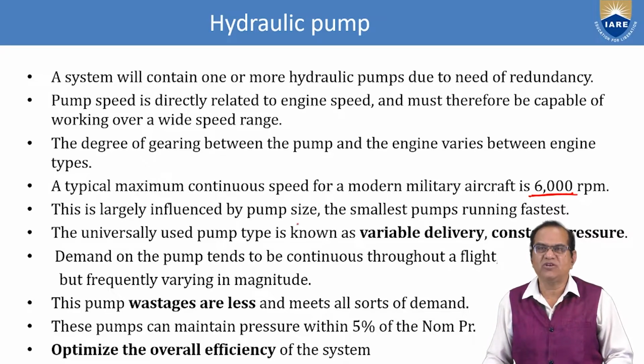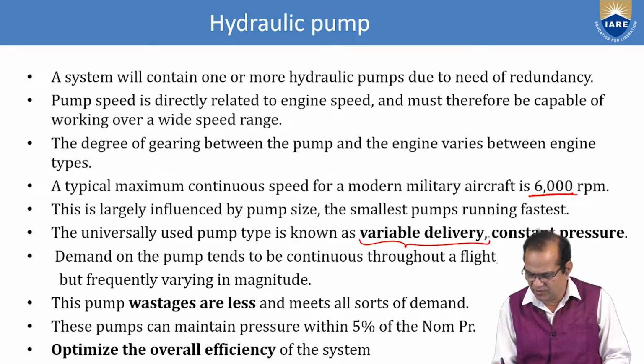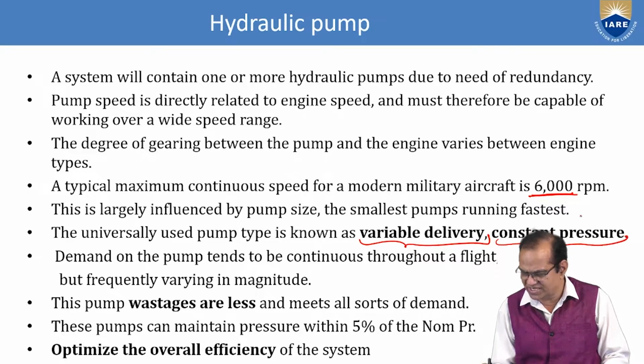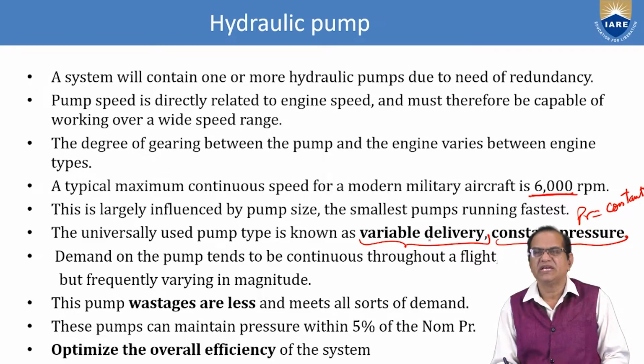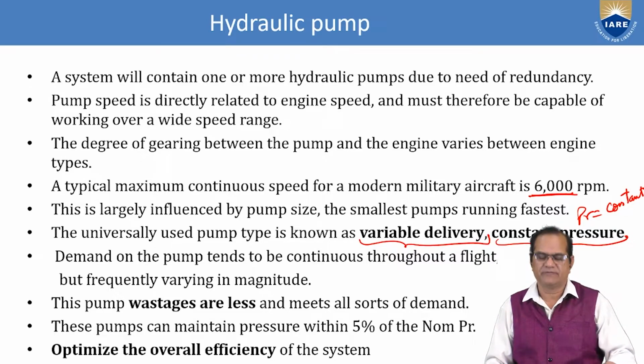The universally used pump type is known as variable delivery constant pressure. Mostly we use variable delivery, and the pressure we make constant, and the delivery flow is varied as per the requirement.